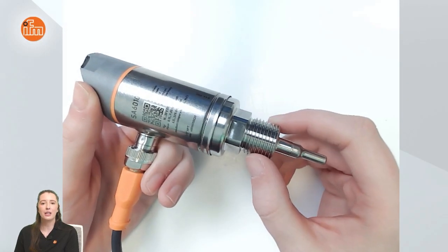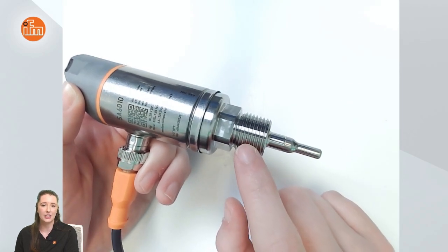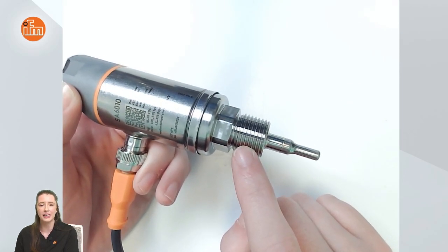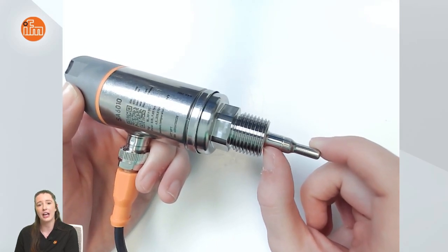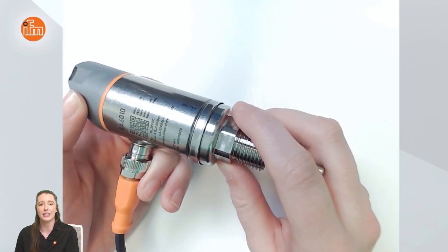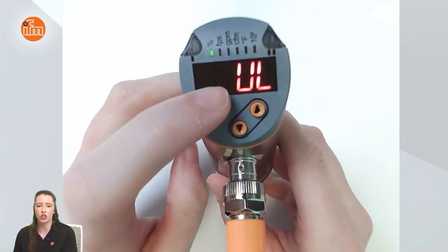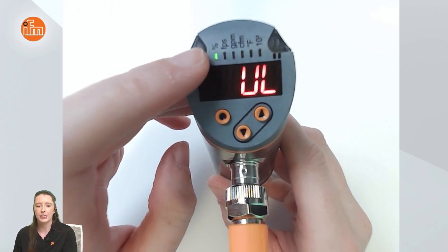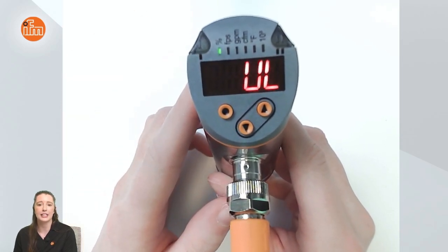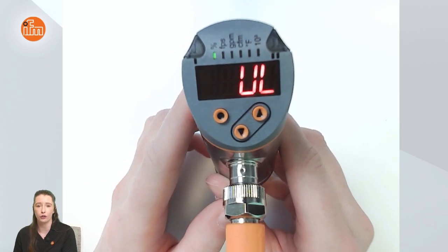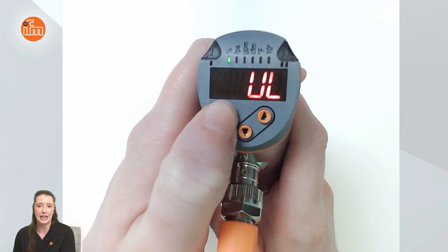So in this video, I am going to program an SA6010 sensor. As you can see, this specific part number has a 1/2 inch MPT process connection and a 26.6 millimeter probe length. As always, we have other SA options available with different process connections and different probe lengths. To begin, you can see that the display is showing UL, and it has a percentage LED lit. That is because this sensor comes factory set for relative mode and it has not been taught its high and low flow conditions yet. So to begin, I'm going to take you into the menu by pressing the enter button.